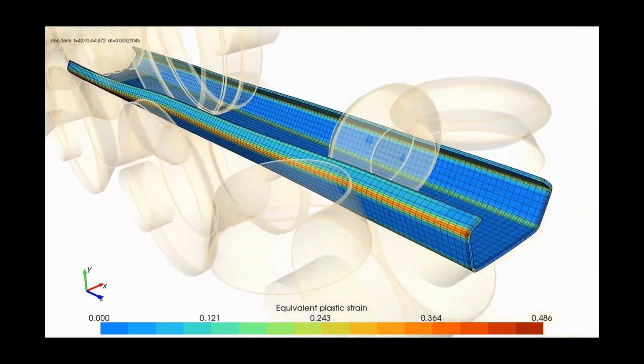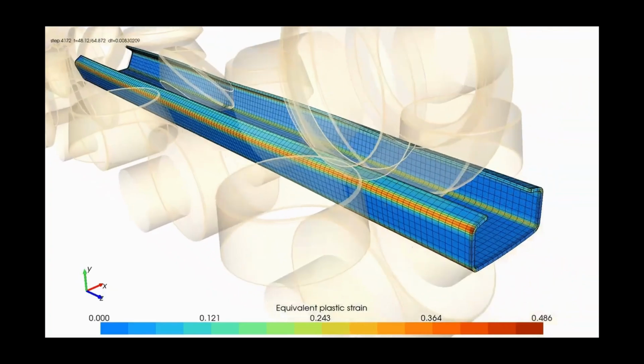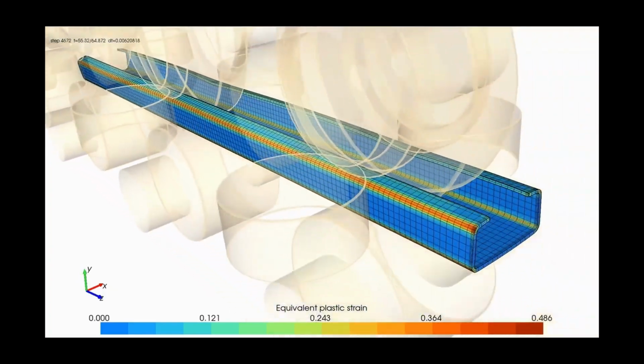Typically, calculations are performed to determine the optimum corner radius, taking into account the thickness and type of material, as well as the end use of the bent sections. Using computer modeling can also help determine the best radius for a particular application. Corner radius can significantly affect the number of passes required to bend metal in a rolling mill. Here's how. 1. Smaller radius.